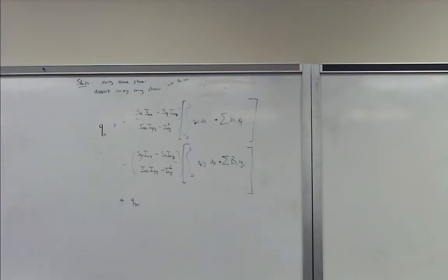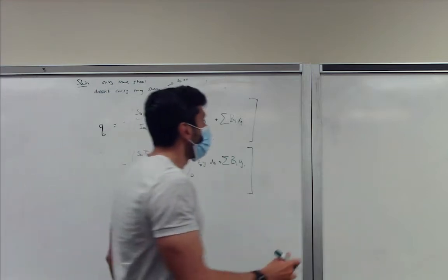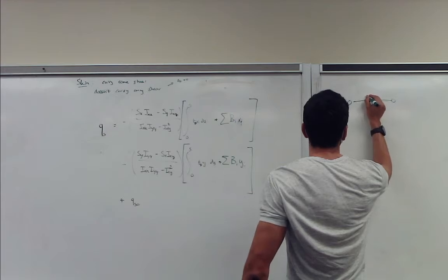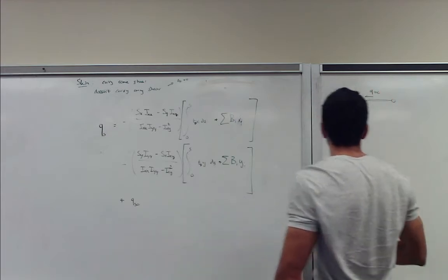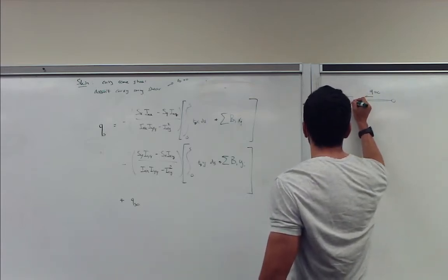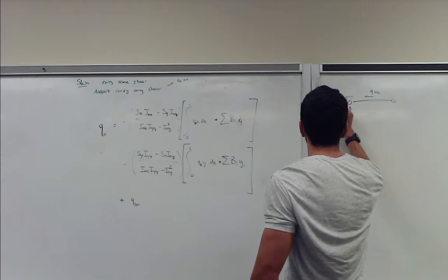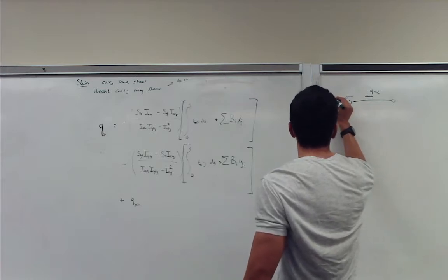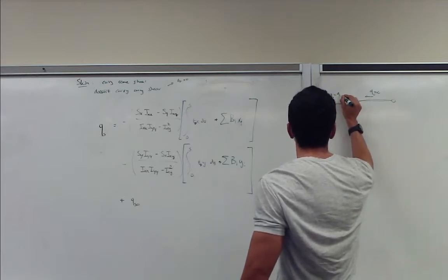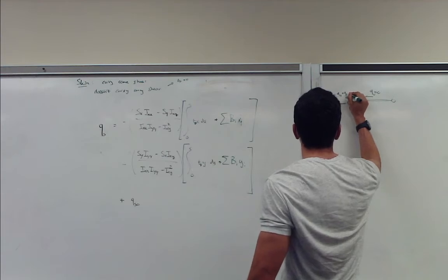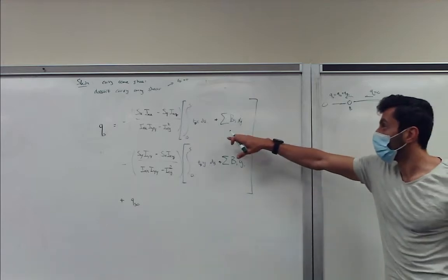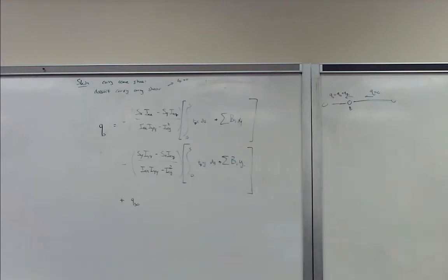And we assume that between two booms, or the shear flow between two panels, q is a constant, and shear flow can only increase when we pass over a boom. So we have another boom, and say this is q0, and then q1 will be q0 plus the boom contribution. And that's listed in the second part of the equation.